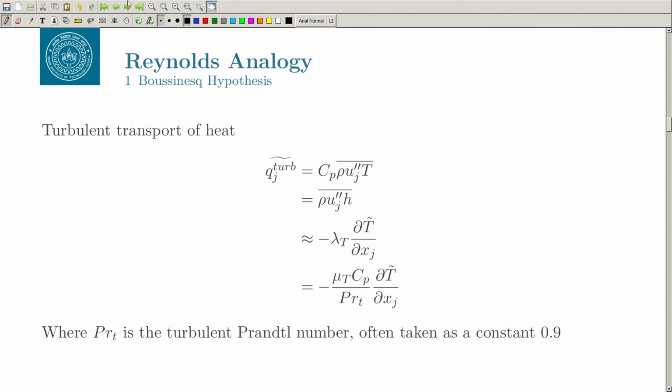Now, as we saw earlier, we have another issue in the compressible flow, that we do not know this term. There are many other terms which we neglected in the compressible flow, which were basically related to the viscous diffusion of the fluctuation term, or the correlation of fluctuation term, but this is the turbulent transport. Basically this is the fluctuation uj double prime, which is basically transporting the heat, right.